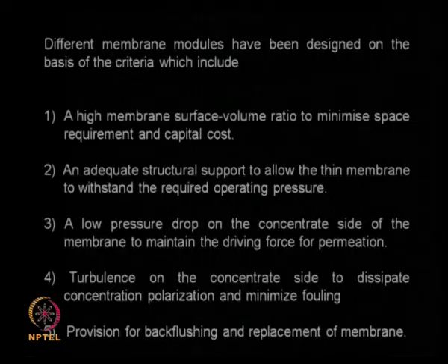I should also have the provision for replacement of the membrane, because you may be doing back flushing many times, but after some time the membrane has been fouled so much that there is no hope of recovering its performance, so we may have to replace the membrane. So there have to be facilities for performing this type of job as well.